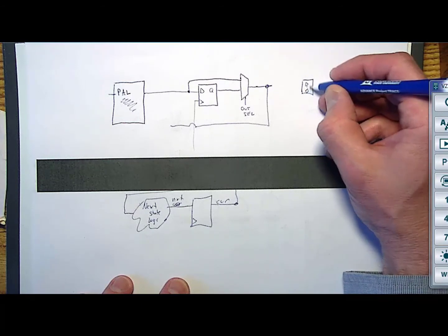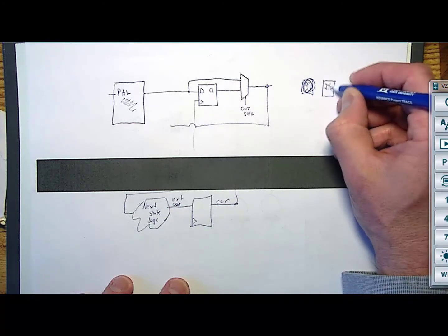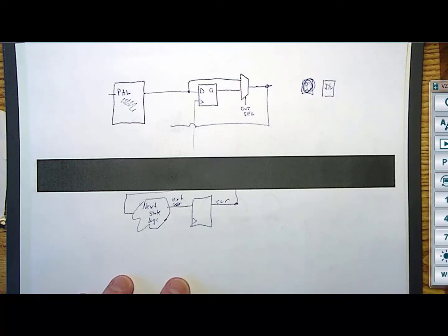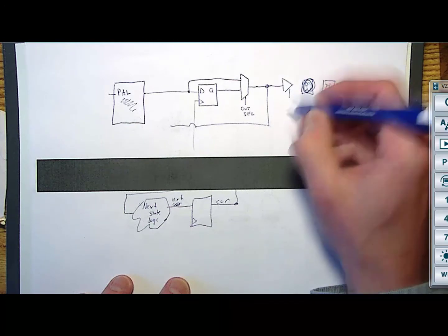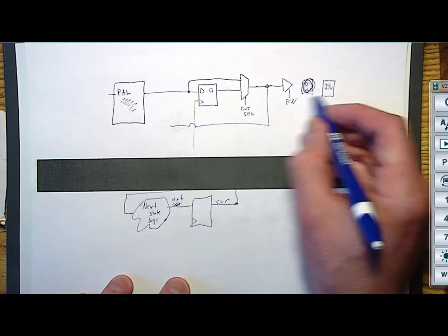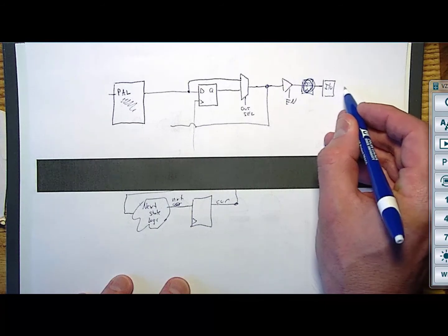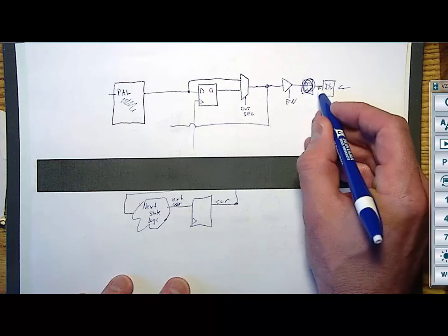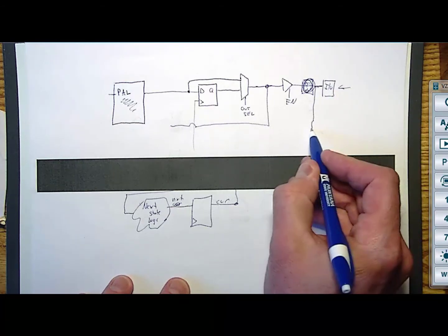So they drew it like this. They have an I/O pin or groups of pins. And then they would have a tri-state buffer which would allow it to either drive to the outside world, or if you wanted to bring this in, you could wire this now as an input into the programmable logic.